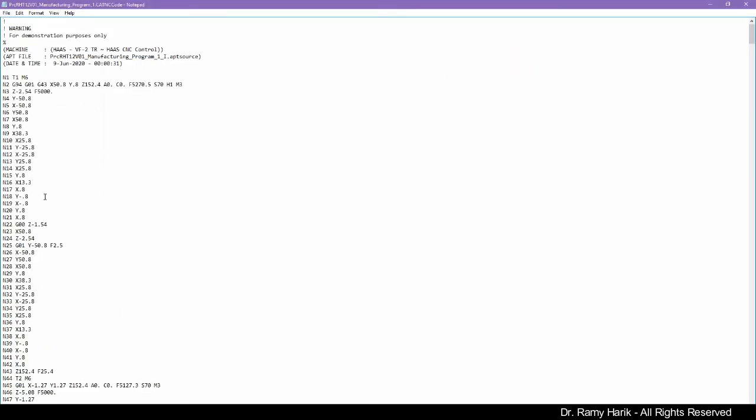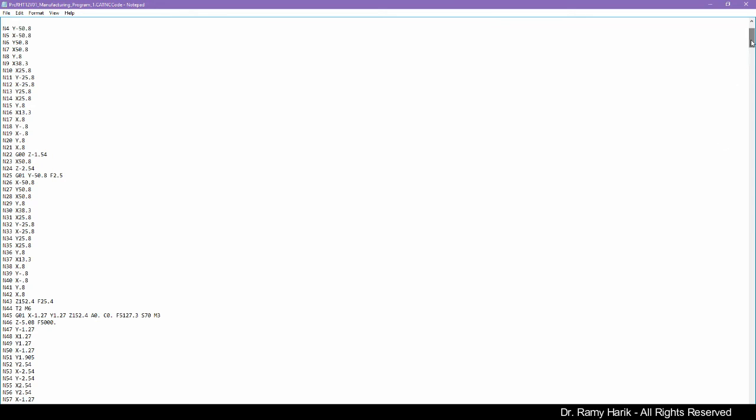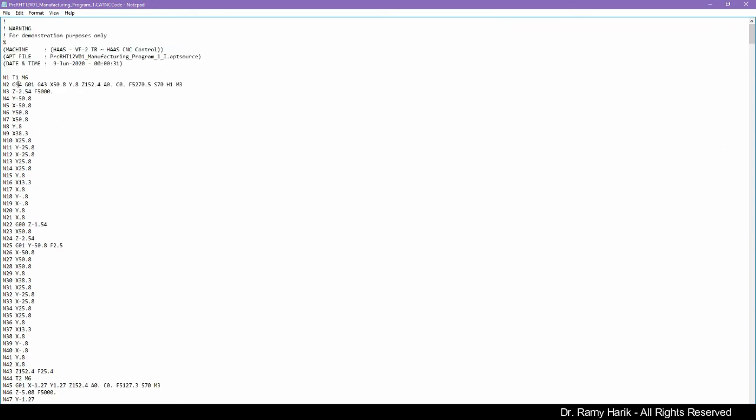So this is the end of this tutorial. This G code is very useful for you to read, and it shows you a little bit of tool change, machine setting, some feed rate going to certain points. There are different geometric motions, and then you can see the manufacturing starts in here because the feed rate has been set low, and we have linear motions like G1 and so on.